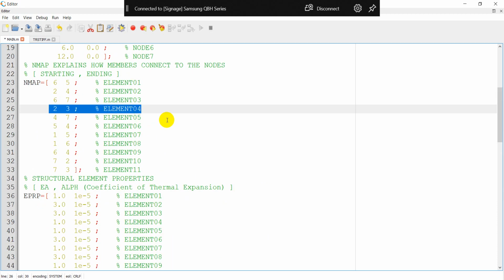So you look at the element number 4. The first two entries, first two rows and columns are for the DOF 3 and 4. Right? 3 comes from 2 multiplied by 2 minus 1, and 4 is just 2 multiplied by 2. So first two rows, first two columns are for 3, 4, and then the next node number 3, the associated degrees of freedom are 5 and 6.